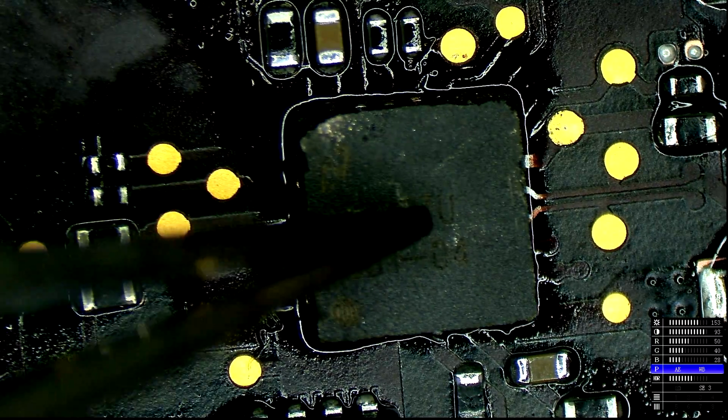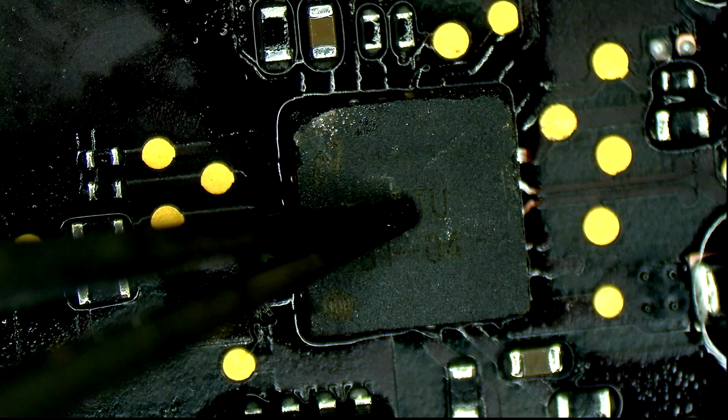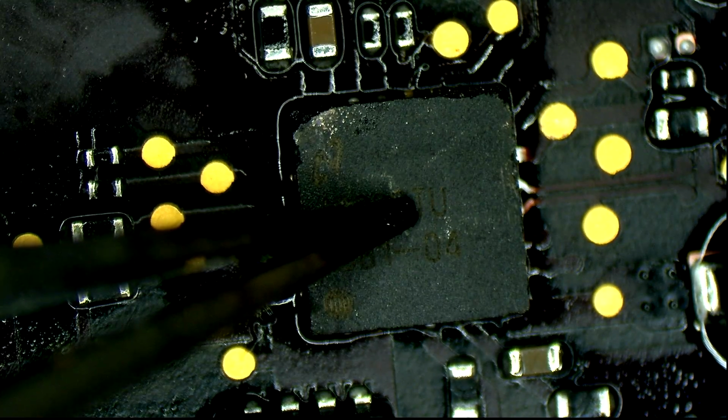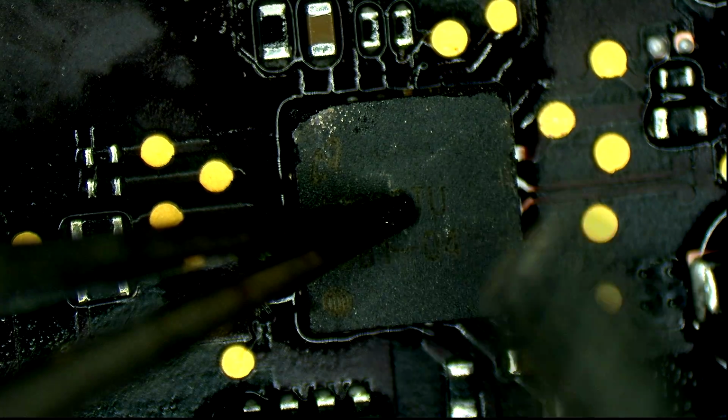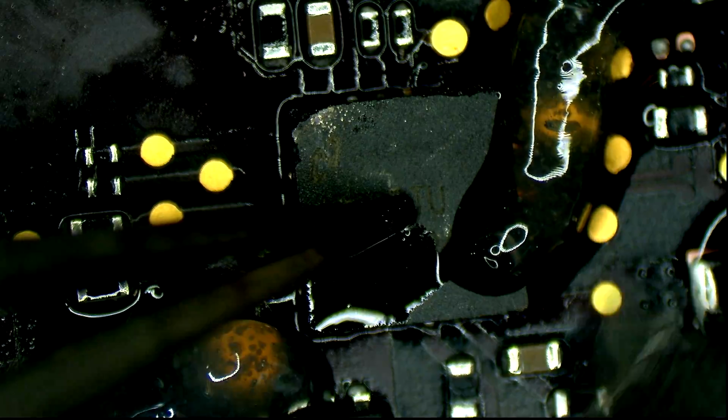Here we go. I made it dance a little just to make sure it's aligned. Once it's dry, I'm going to push down on it and then heat it up one more time just to make it nice and flat on the board. Make sure it's making good contact. Add some flux before I do that. I don't want it to move from side to side, as Ariana would say, but I want it to just go straight down.